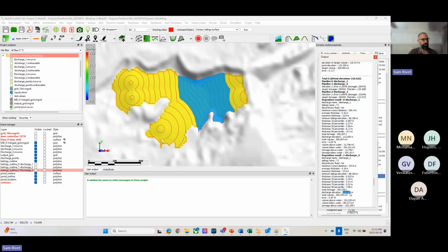119.428. So, discharging 250,000 cubes here realistically would result in this discharge line at 113 meters in elevation, if that's where it was, getting buried. So, if this line was really at 113, we need to place less tailings out of this location. You can see the discharge line is here, but the tailings backed up a lot further, buried it because that was just too much volume.